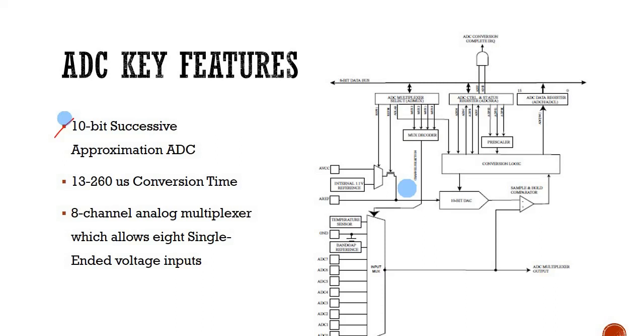But at the same time, there are dedicated ADC modules out there, and if you think that you want something a bit better than what you already have in your controller, then you can think of getting an external ADC module and then interface that to your current microcontroller. But in our case, since our microcontroller already has an ADC module, we will be using it. Since we have a 10-bit ADC, that is what we will deal with.